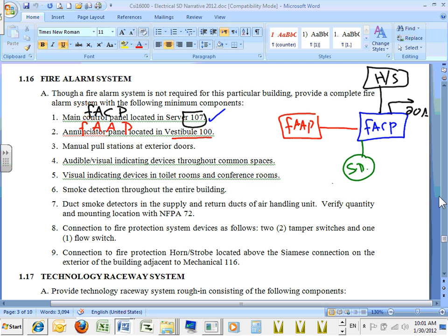Fire alarm annunciator panel, guys, this one usually you put in a place accessible to the firefighters. When they walk in right down at Dunwoody at the beginning, you have a red panel that has all the zones on it. So if you have a fire in a building, it announces the location of that fire. A building like Dunwoody has multiple zones.